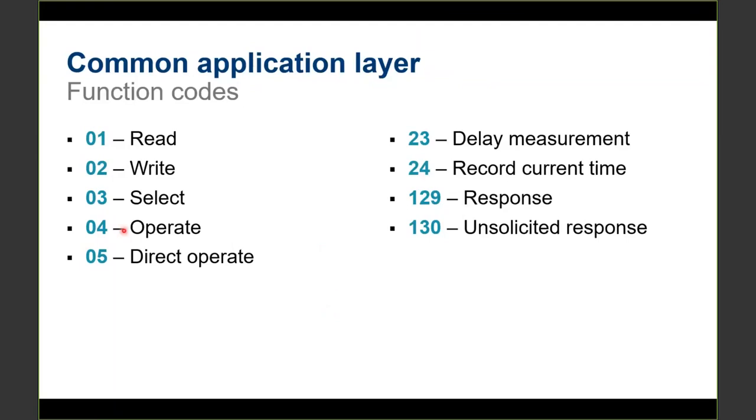So when we see a response from the relay for direct operate controls, the slave station can respond, for example, if my master station sends a direct operate control to the index, let's imagine one example, 99, and the relay doesn't have this digital output in the DNP map. When the relay responds to this message, the relay will put a status saying, I don't have support for this DNP index. And this behavior really helps us to troubleshoot problems.